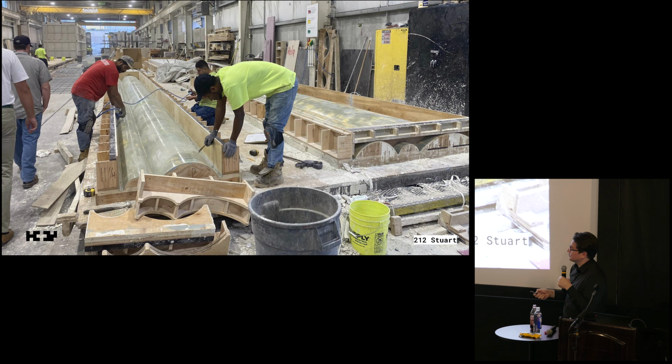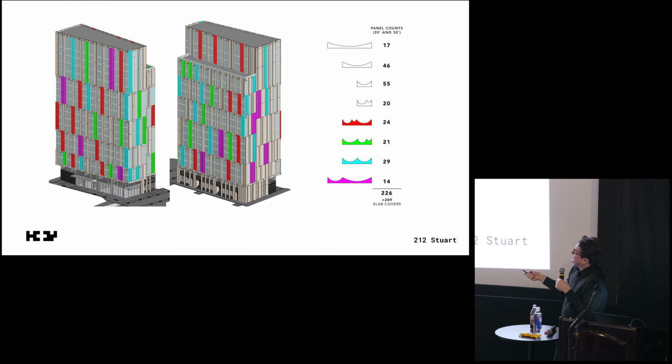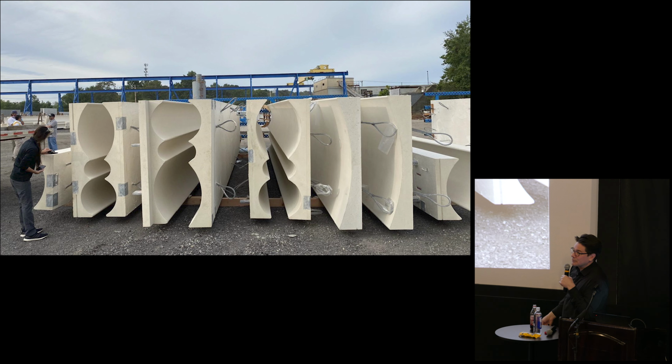We thought it would be beautiful to get these shapes optimized. Initially we optimized it for the mold, thinking we can do a couple of molds and get all kinds of variation or repetition. Turns out they needed to be optimized for the crane. Right? Crane time is the expensive time. And so rather than have a bunch of little pieces, we had these bigger pieces that were really efficient to pick and to place.